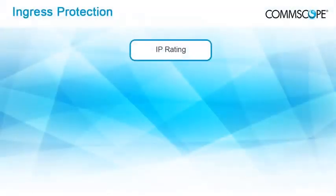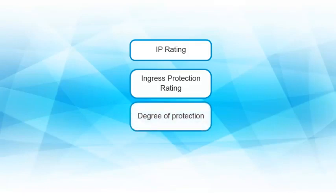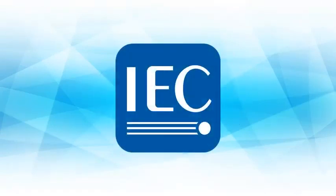IP-rated closures and connections follow the IP code or Ingress Protection Rating, also known as International Protection Rating, which outlines the degree of protection provided by enclosures and components. They also classify and rate the protection against solid objects, including human body parts like fingers, dust, and water. Published by the IEC, the rating's goal is to provide detailed information about specifications for waterproofing and more.